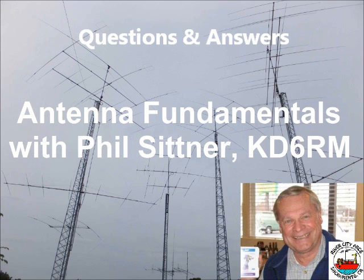And so with one of these, you can actually take your feed line. It goes to your antenna. At the end of the feed line, you can perform this calibration. There's an open connection, a dead short connection, and a 50 ohm connection. The computer measures what goes on at the end of the piece of the feed line, which allows you to measure the antenna at the antenna itself.